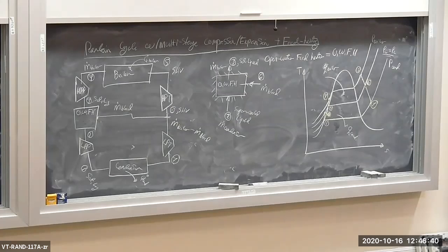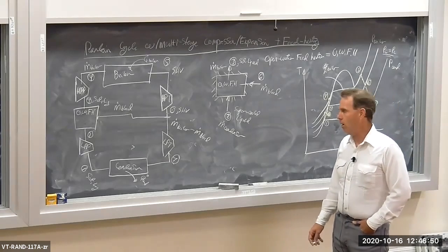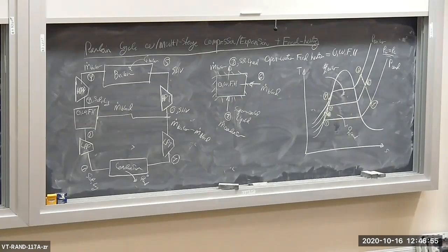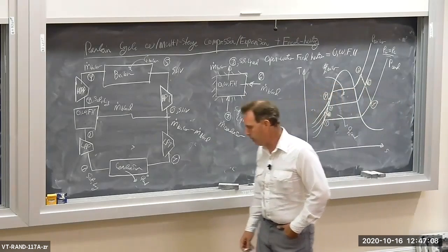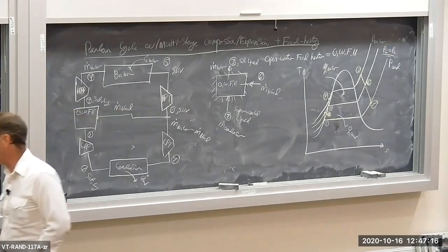So power plants, and, well, power plants on ships as well. Propulsion plants on ships, which often are operating off of a Rankine cycle, especially the old ships that were oil and coal fired, those have various open water feed heating systems as well, okay? So this open water feed heating gets you an extra percent or 2 in efficiency of a Rankine cycle. Not as amazing an improvement as with regeneration in the Brayton cycle that we looked at last time, okay?